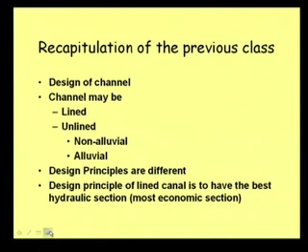How to obtain that sort of critical velocity is again a very challenging task, and for that purpose empirical relations are generally used, that is, equations derived on the basis of a lot of observed data of stable channels. Of course, some semi-empirical theories like the tractive force method are also applied. In the last class we saw that design principles are different for different types of channel, and the design principle for a lined canal is to have the best hydraulic section. We started with the design of a rectangular channel, and completed up to the trapezoidal channel.